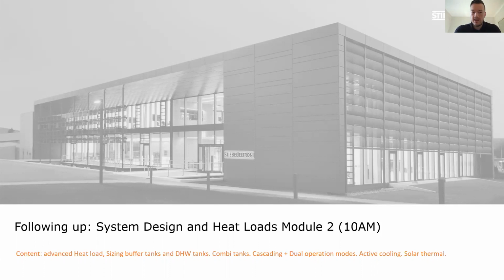If we have more information, like air tightness, blower door tests, all types of performance reports for buildings, then we will use different tools, which also include, is this place windy? Is it in a sheltered location? Which sort of feeds into air tightness, and that then adds a mathematical factor to the equation, which will inflate the heat load or cooling load for sure. So long story short, it probably depends on the model that we use, and that is contingent on how much information we have. Hope that's good enough, James.